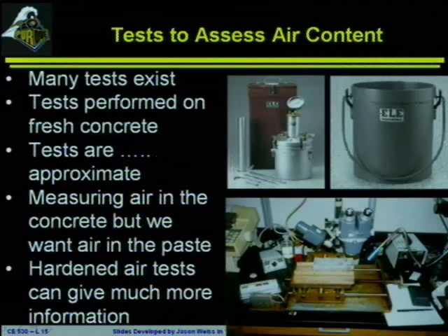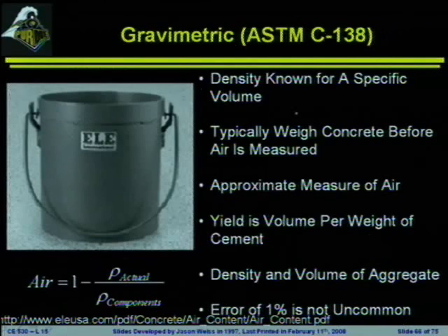Some of the test methods we'll talk about for air entrainers. There are several different tests that can be performed. Some are performed on fresh concrete, some are approximate, some are performed on hardened concrete. I'm going to go through these fairly quickly, and I'm going to point out the fact that we still don't have a really good test for determining the air content of concrete. And there are a few reasons for this, which we'll try to hit as we go through.